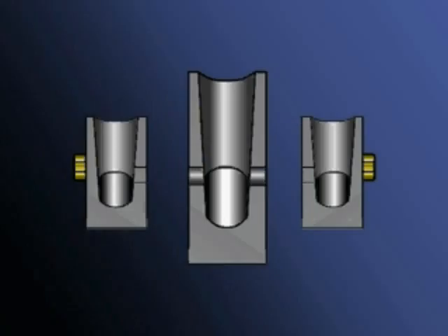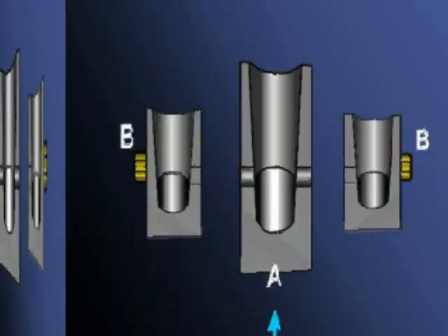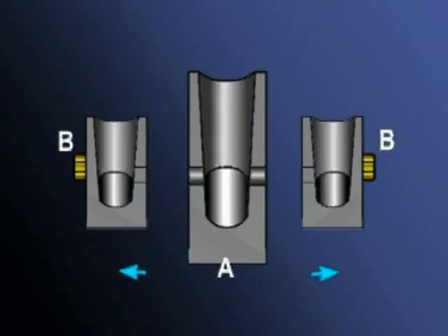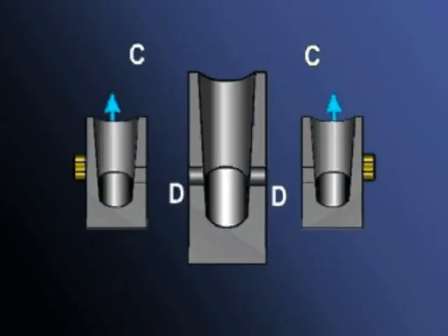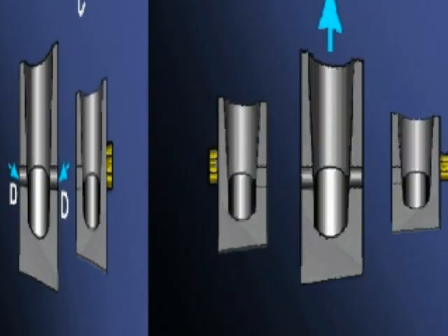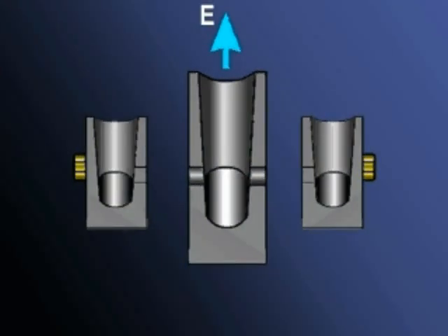This diagram shows a two-stage double suction pump. The suction at A is split into two and fed to the first stage impellers at B. The discharge from these impellers, C, is fed to the intake of the second stage impeller at D. Final discharge occurs at E.